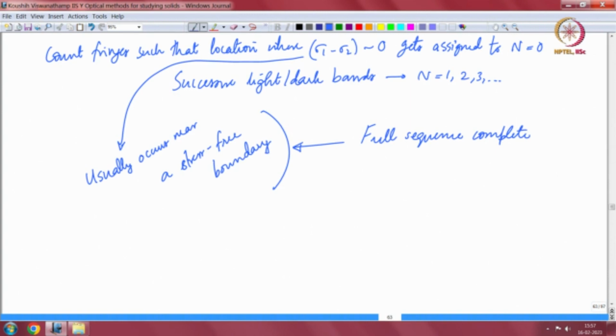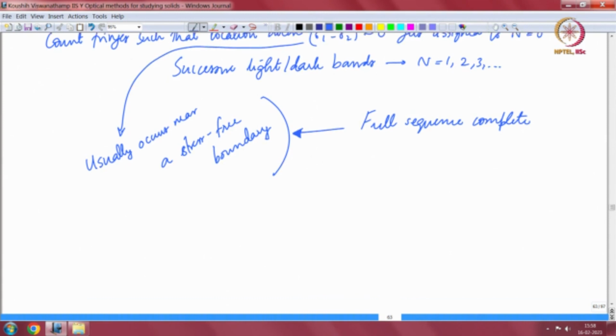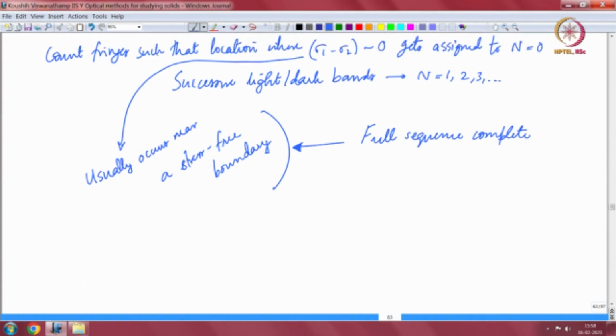So, in principle you can superimpose a hydrostatic pressure and you will not see a change in the fringe pattern if it is purely elastic, but nonetheless you will get a full field recovery for a plane stress deformation problem. Now, the mathematics is fairly simple, the algebra involves some matrix manipulation and so on, but we should be able to calculate, given any situation, the stresses in a particular object, at least the principal stress difference and the orientation of the principal stress directions.